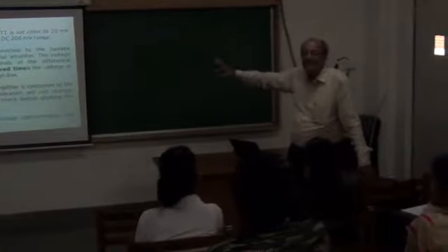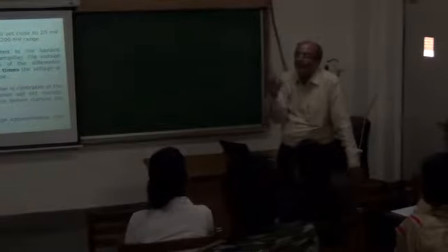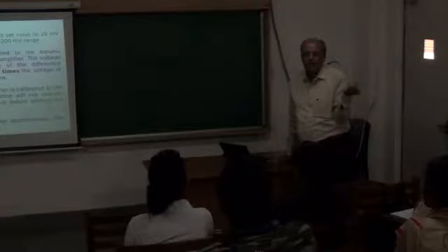Matched pair of transistors: you should study it, because normally in textbooks we say those two transistors are the same. But please study about matched pairs. What do you match? Why is perfect matching impossible? The beta value will be different. The beta value will also be different.